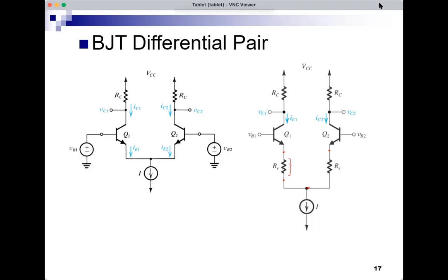And now you know also why we don't typically use it in the MOSFET differential amplifier, because in the case of the MOSFET differential amplifier, the input resistance is infinite anyway. So we don't need to increase it. It's already infinite. And the characteristics of the MOSFET are not as nonlinear as the BJT to linearize them. The parabola is closer to linear than an exponential is. So again, I don't need to linearize and avoid distortion the same way I need to do that with BJT.